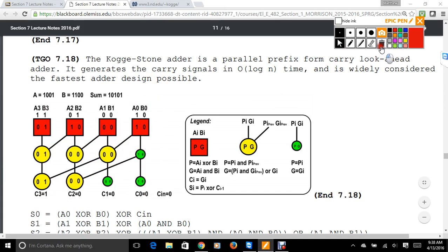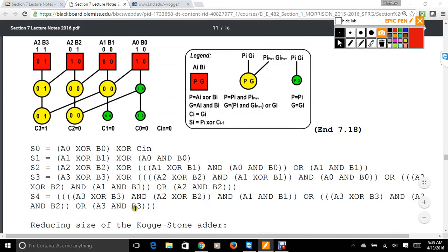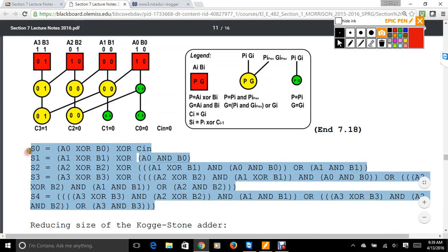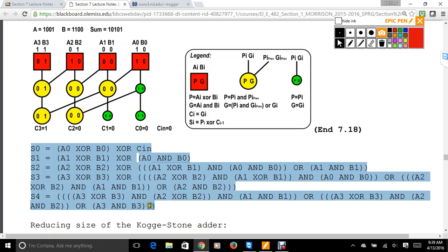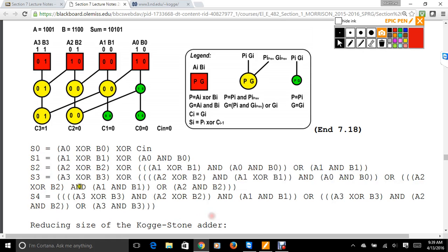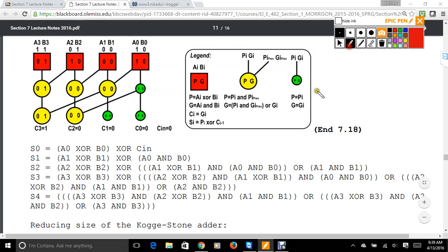So that should significantly reduce your time. And so these become the logic that's generated as a result, right? So what ends up happening is you are able to reduce the logic from your carry to be able to figure out what the minimum should be, and as a result, that's how you're able to generate the propagate and generate signals.